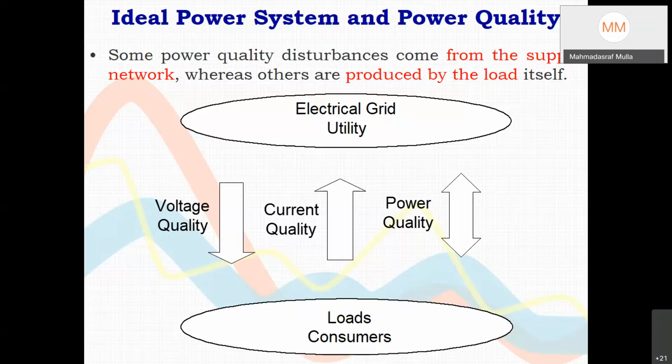That is the optimum case, where we don't have any power quality issues, with pure sine voltage and current in phase with each other. And all transformer volt-ampere is converted into wattage. So a 100 kVA transformer can provide 100 kilowatts of power, provided voltage and currents are sine and in phase with each other. So this is the ideal desire, and the deviations will come from these 3 points: majority of the time from the load side, many times from the supply side, and some of the time from some heavy load connected at the same point of common coupling.